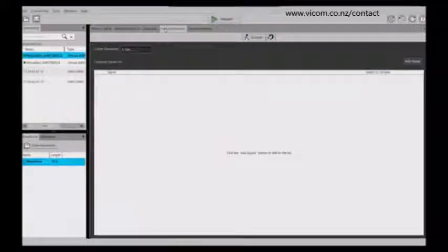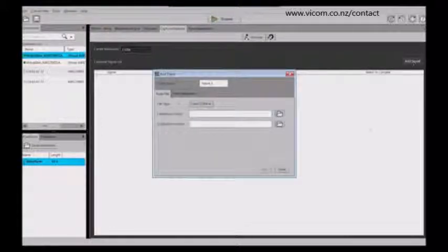Capture and playback gives you the capability of up converting or down converting a signal. So if you have an IQ type signal, you can add an IQ type signal, or you can use an IQ file, TIQ file, or whatever IQ file you have. You can load that into the system, or if you want to have separate files, you can use each individual waveform. So in this case, if you're using a two-channel box and you want to load two separate waveforms, you can do that.